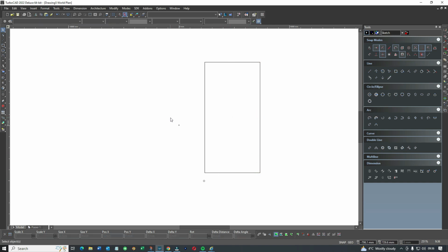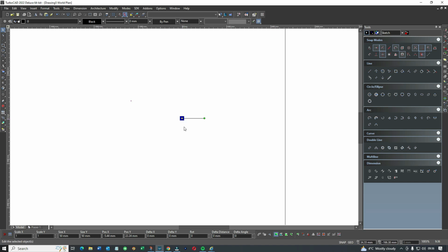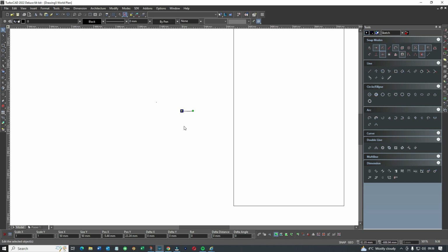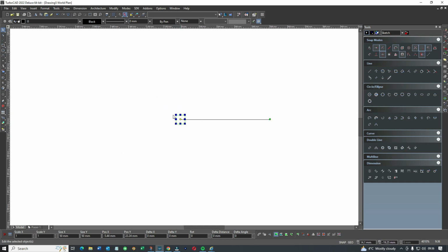Now when we go to print these, we're going to have major problems because you wouldn't print it in the same way. So you're going to have to set up a paper size parallel to your drawing, you probably need to set up a 1:1 page size here to be able to print that properly.